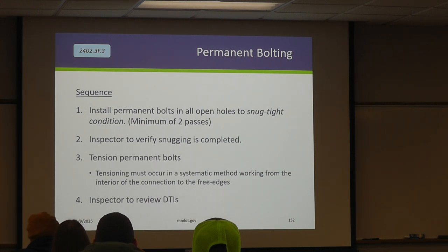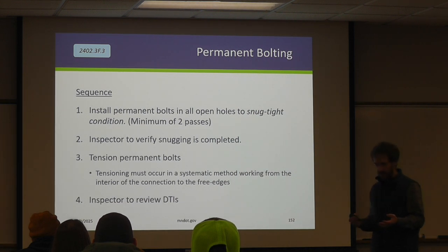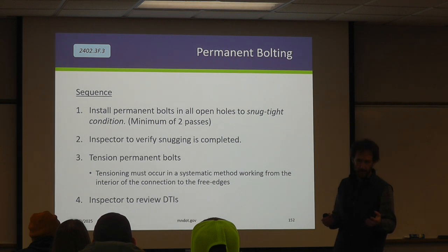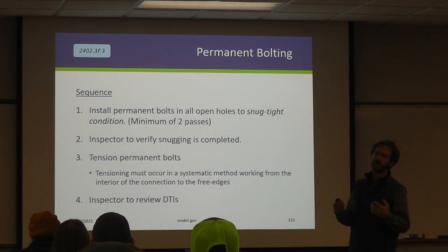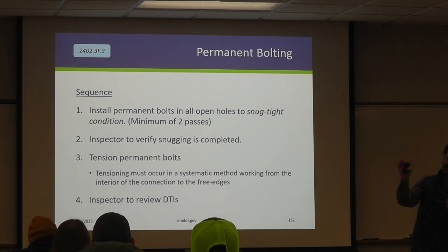A lot of crews have gone to where they're using a 2-gun system because they're using these guns with lithium batteries, where they'll have a gun that is set to a torque that is significantly less than what it takes to fully tension these bolts, and then they'll come back with a second gun that has a rotation programmed into it that they know will get them to this tension.